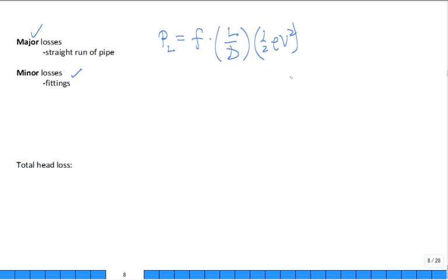Okay. How about for a pressure loss in a fitting? Well, it's proportional to the 1/2 rho v squared in the pipe getting right up to the fitting and through, but they don't have a length to talk about, and so they just put a loss coefficient, typically K, sometimes in a different symbol, but almost always it's K as a loss coefficient.